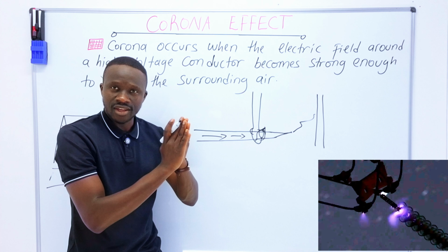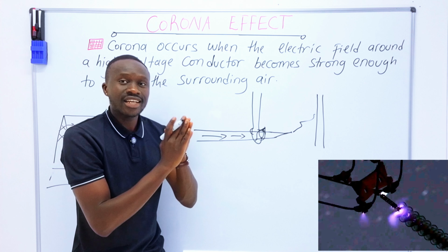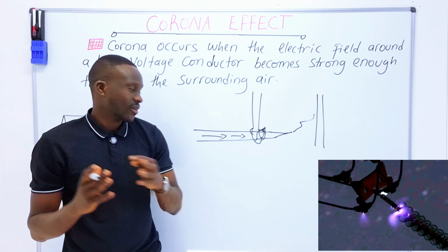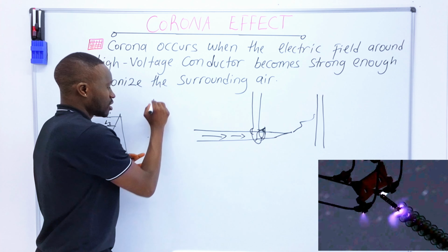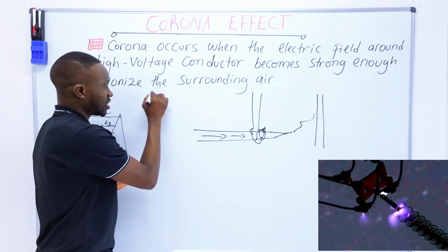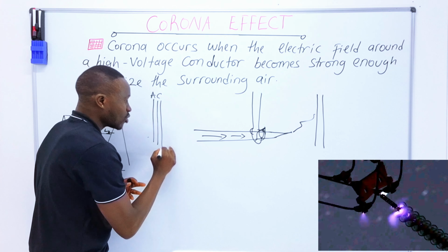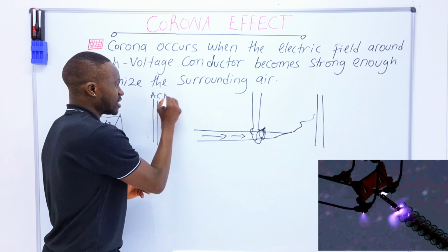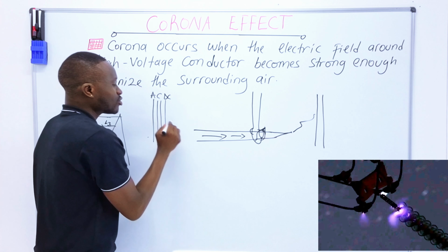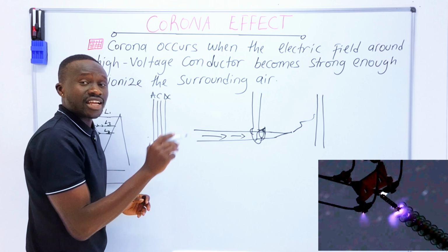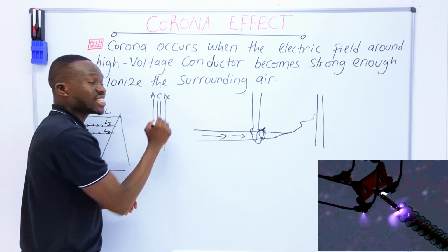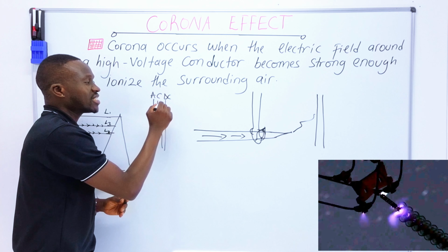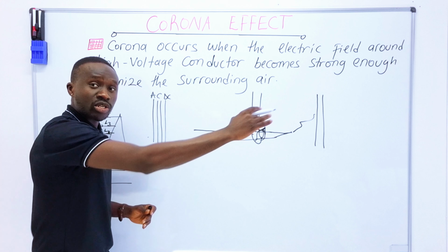Solar is using DC, the battery, and the electrical is using AC, alternating current. Solar is using a direct current. When you put them, this is an electrical AC cable, then you put them in one conduit, it is not advisable. This is a DC. Now remember, electrical AC goes and comes, that is alternating, while this is a direct current, it just goes in one direction.